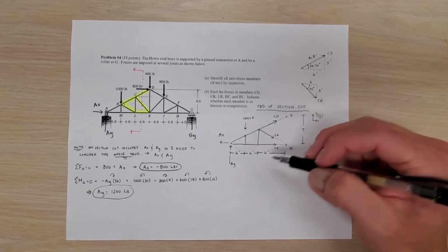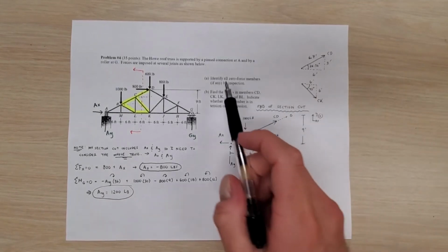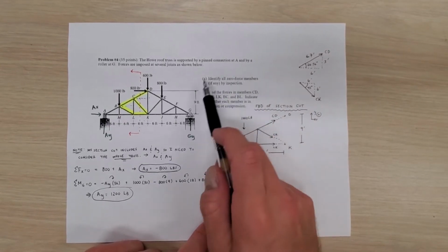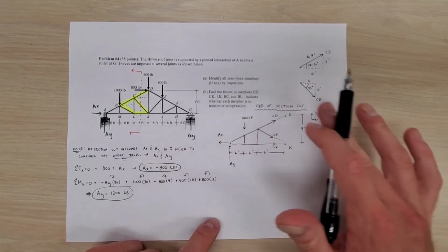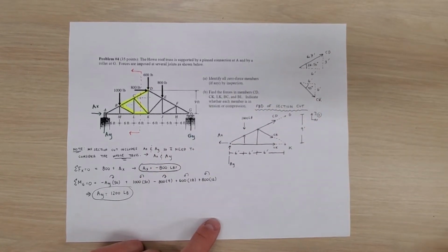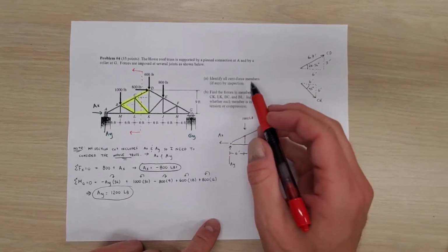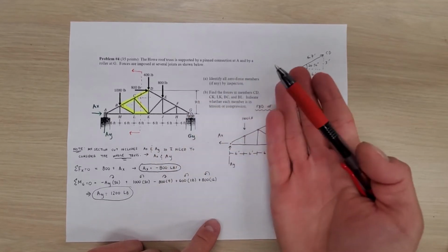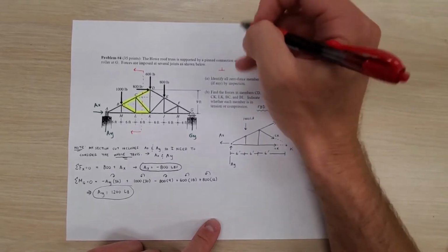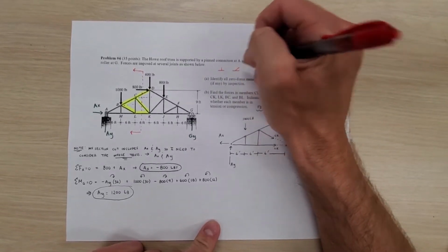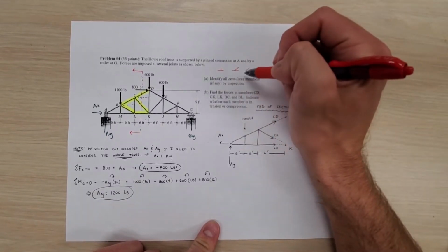And now what I'll do is try and figure out how to solve for all the forces. Now before we do that, question A did ask us to find all the zero force members by inspection. So we should real quick see if there are any zero force members before I move forward with this analysis to make sure that I'm not solving for something that ends up being 0. So zero force members, we want to look for a T. So anywhere where we see something that looks like this, anywhere we see something that looks like this, or anywhere we see a joint that looks like this. So it's one of those 3 things.